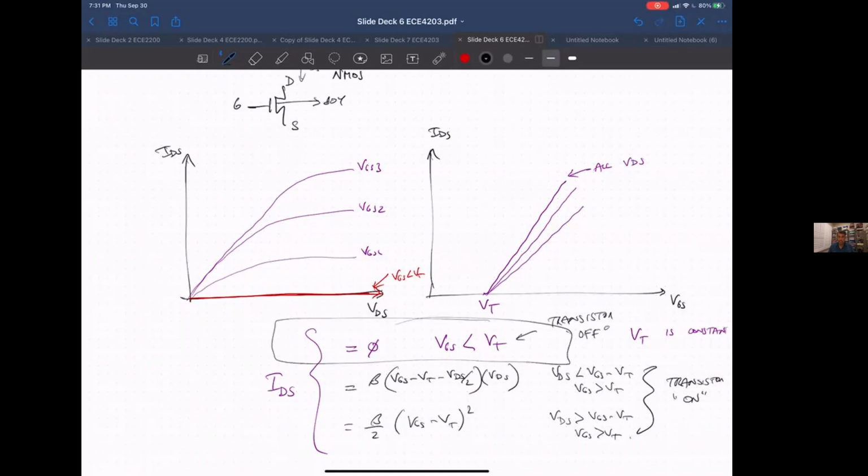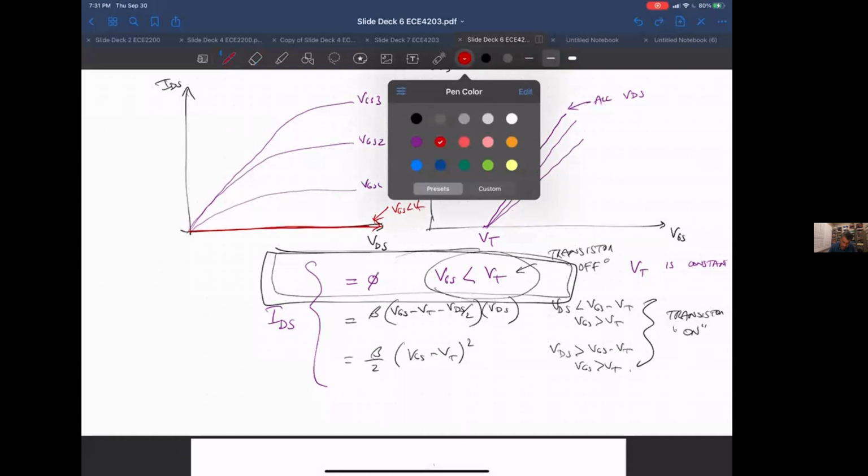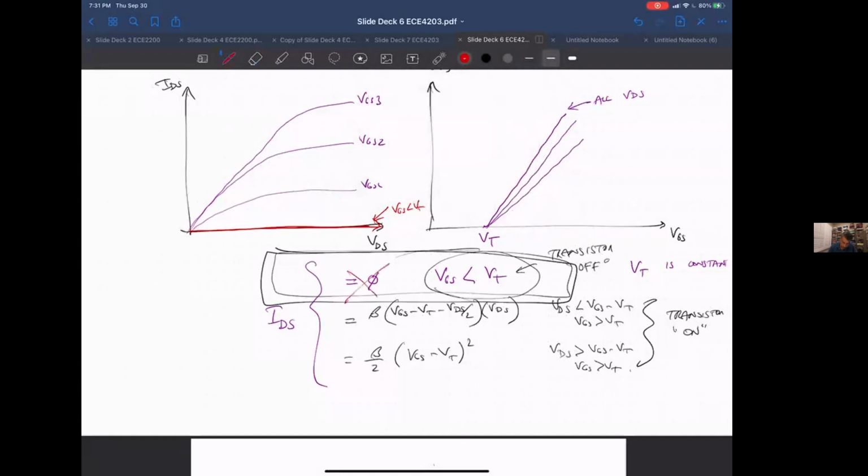Professor. So the first level model is that the transistor is off if VGS is below VT. This was true back in the day when transistors were physically large and all that stuff. What leakage current says is that this is no longer true. What it says is when VGS is less than VT, we will get some leakage current, I leakage.